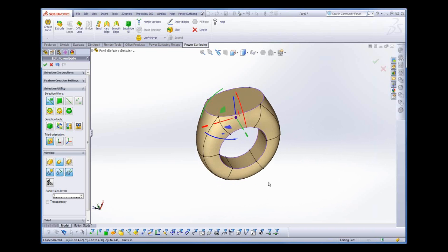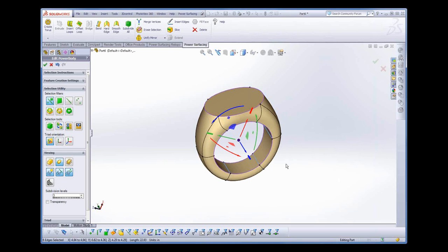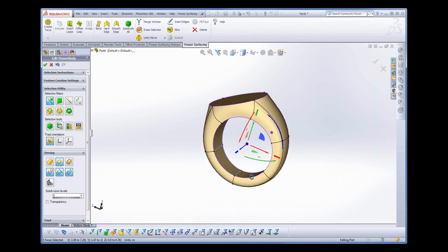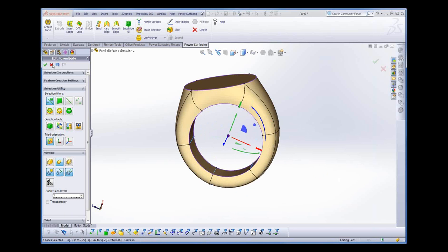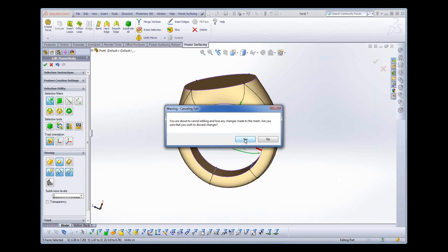Cool. Let's see. We have one from Doug. How do I manage parting lines for a molded part? Oh, very good question. There is a thing on our website that goes through different scenarios of starting with a surface. Let's say you have a single curve that goes around as your parting line. You can create a couple of surfaces off those and use those as starting points in the create from surface. It uses the NURBS subdivision, so you actually will have an exact interpolation of that curve. So that can be your parting line.